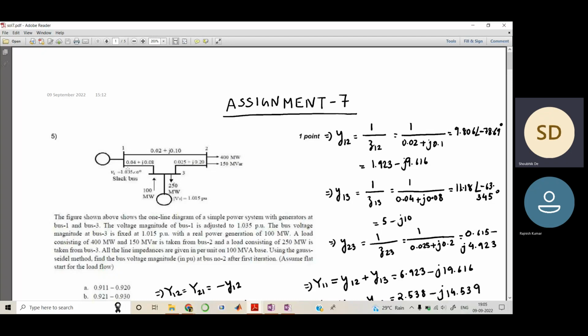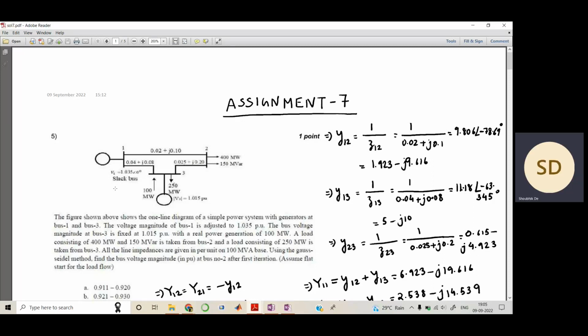So this is a slack bus. As you know, what is a slack bus, I did not say. These are reference buses for calculating the power losses, and generally we consider one of the PV buses as a slack bus. And for this bus number 3, here you will see that V1 is at an angle of 0, right?